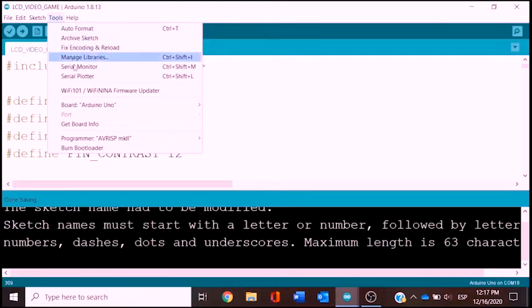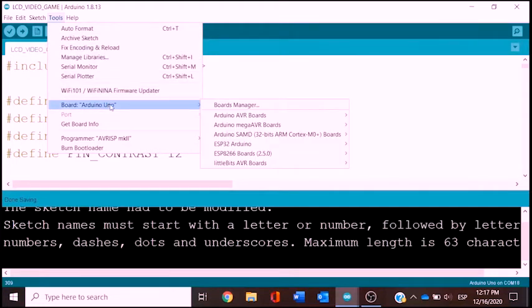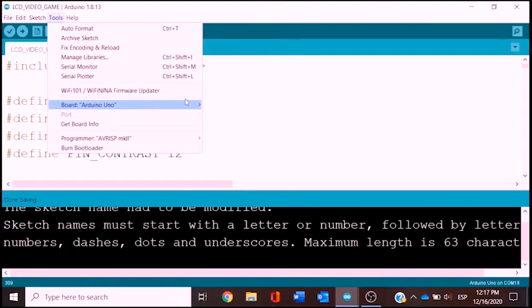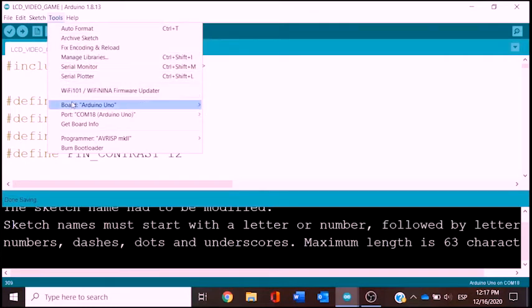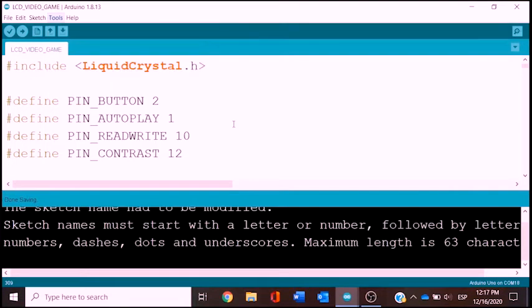So in here we are going to look for Arduino Uno, which is already here. Since we have our project connected, we're going to click on Arduino Uno, and then the next thing, looking for a port. So the port is already here. When it's not here, we look just in serial ports, and the program will find it. So we click on this one.